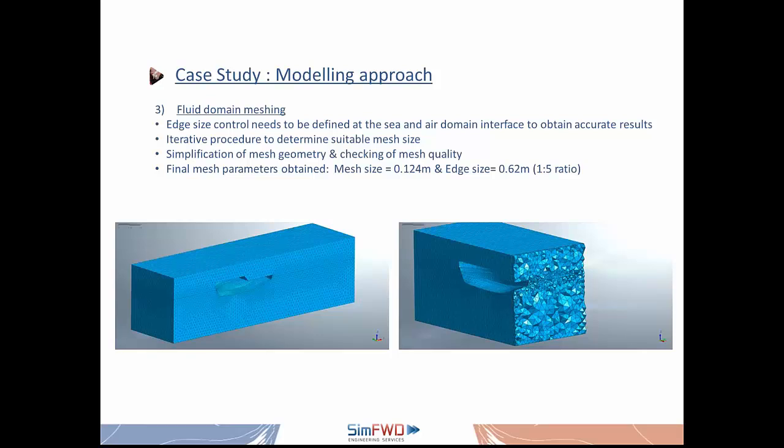What we have utilized in Midas NFX is the available automesher, which is very quick and robust. It is advisable that when starting a project, as a first iteration, you always give it a try with the automesher and see what the problems are and how you can refine them at a later stage.